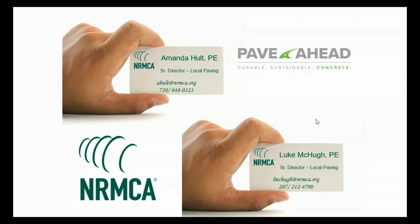All right, thank you. Next question. Please comment on the effect that the bond between base and concrete surface has on the potential for cracking due to restraint. What types of bond breakers do you recommend when using asphalt or cement treated bases? Brian, this may go, and I don't know if you get into this in your soils webinar, but typically we do not call out for a bond breaker if we do a cement treated base.